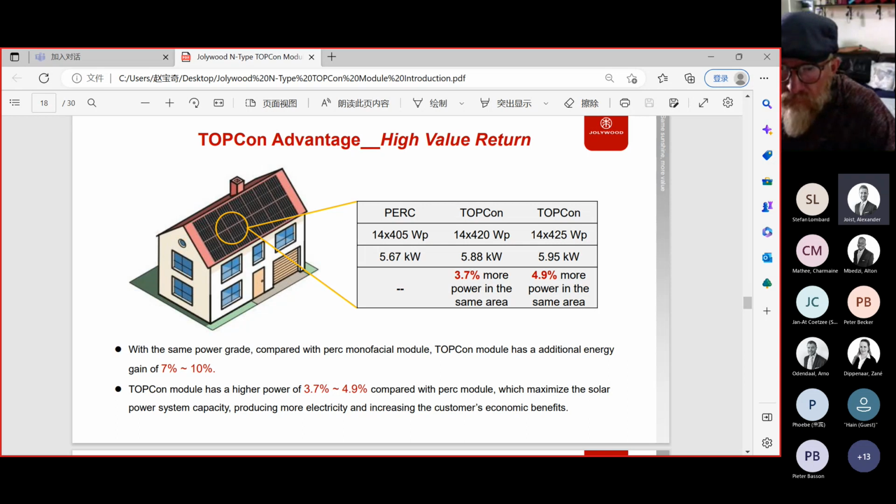I know that it's normally just a software update, because the inverters can normally handle even more than 15 amp. But if they have a higher amp input, they're just going to show you a fault in the display or on the system. On most of the inverters it was just a software update from 12 to 15 amps. But everything up to 15 amp should normally be fine for all the new modules coming out at the moment.